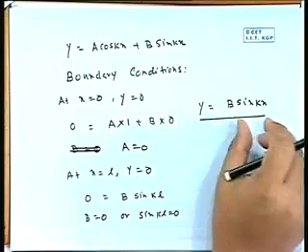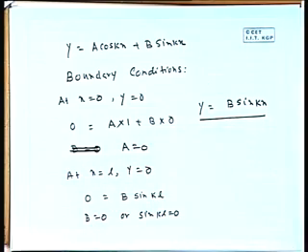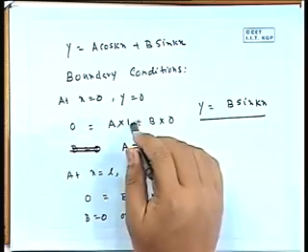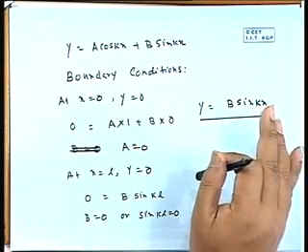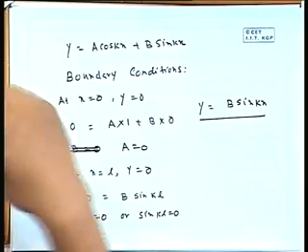Now the other option, if B equal to something, it is a non-zero quantity. Now sin KL should be equal to 0. If B equal to 0, the entire solution will be 0. So that is the pre-buckling condition. Now we want to get something else. What is happening at least when the equilibrium is neutral equilibrium and the load is at the critical load level.